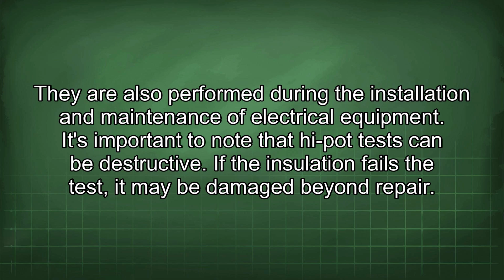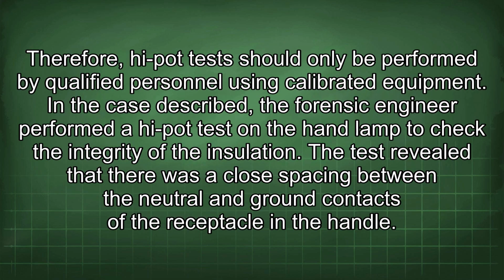It's important to note that high-pot tests can be destructive. If the insulation fails the test, it may be damaged beyond repair. Therefore, high-pot tests should only be performed by qualified personnel using calibrated equipment.